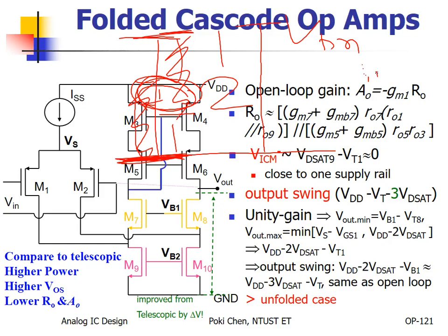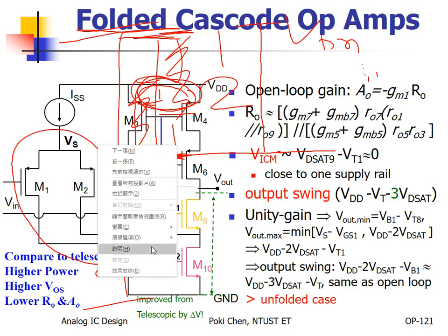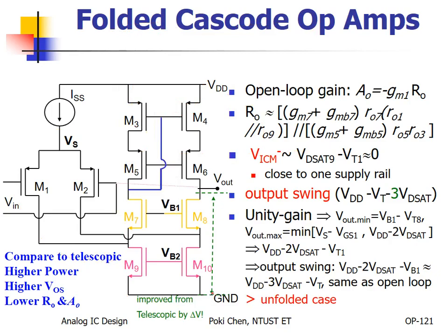Okay? Don't forget the limitation for your operation range. Never mind your input or output. Usually, in analog IC design, they focus very much on output. But sometimes, you still need your input to operate with full range, from the top to the bottom. Then, only one pair means not enough. You need 2 pairs. Okay? Got it? To the end of the chapter, you will see such kind of rail-to-rail operation. But I teach you in advance.